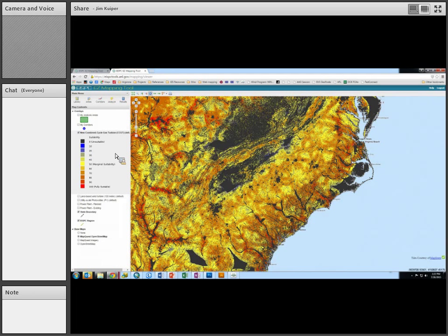So right now we're looking at a suitability map for the combined cycle gas turbine. And so one of our siting factors is we want to be close to water, so you're seeing some higher suitability areas near water, okay? And all those other siting factors are coming into play. These black areas are areas that are inappropriate, so they could be a national park, or these look like distance zones, so this would be an area that's quite far from a natural gas pipeline of a sufficient capacity. You can inspect all the different inputs and find out the results.